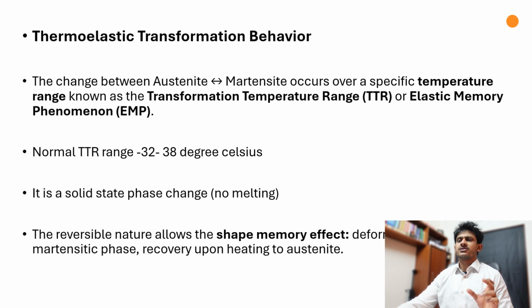And the reversible nature of shape memory alloy is another thing we should keep in mind. It can go between the Martensite and the austenite phase depending on the temperature over and over again, and it's not a permanent change at all.